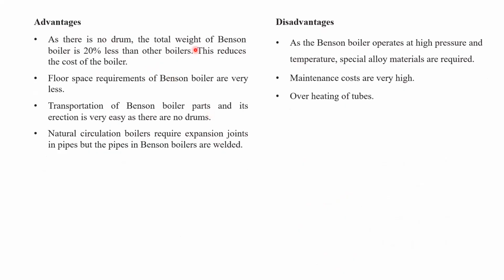As there is no drum, the total weight of the Benson boiler is reduced by 20%, less than other boilers. This reduces the cost of the boiler. Floor space requirement is also less. Transportation of boiler parts and their erection is very easy compared to other boilers.